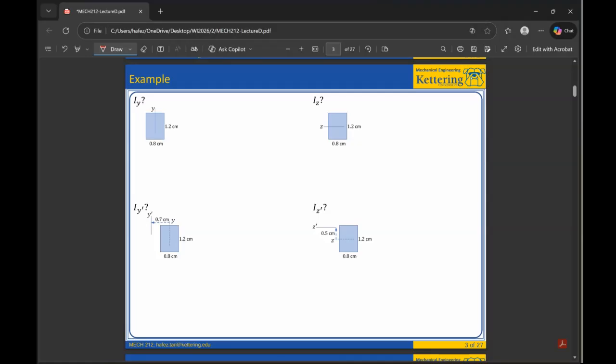All right, so we said let's go over just the I calculation, and you should expect that to be purely mathematical. So it makes sense to do that once for different geometries, learn it, and then really switch to our common sense engineering discussions. All right, so we said I is the second moment of area. And when we say that, it's always defined with respect to an axis, because it really matters which axis you bend about.